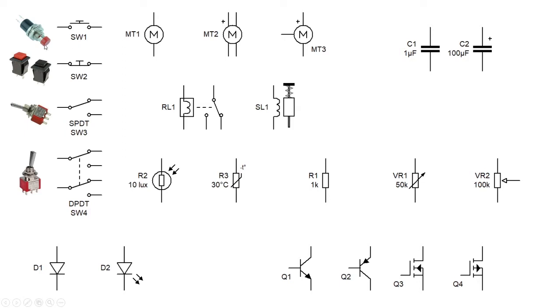We've got switches. They come in different shapes and sizes, but we've got push switches or momentary switches, which means they won't stay in the state that you just activated. So you push to make, in this case. This will normally be open, so you push it to close it. This is called push to make. So you push to connect this circuit, and then when you let go, it'll disconnect and be in this state. Normally open, it's called.